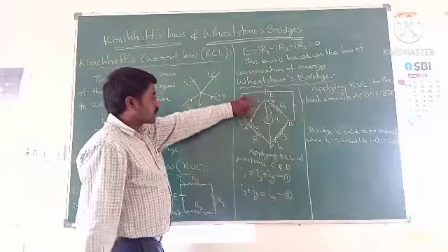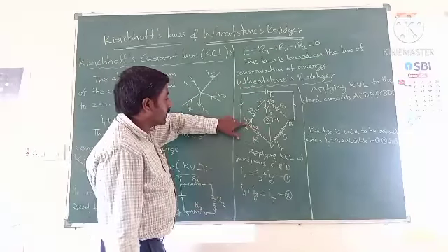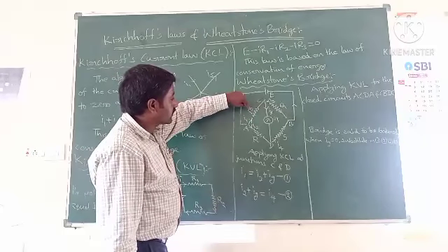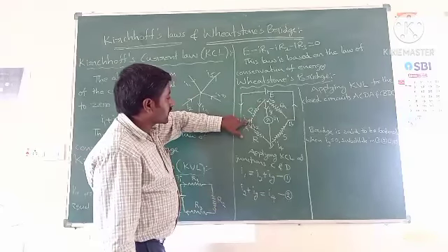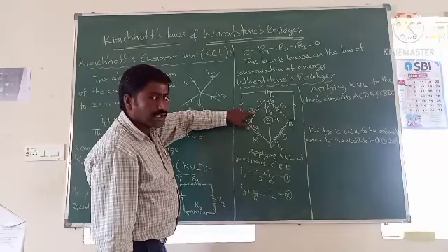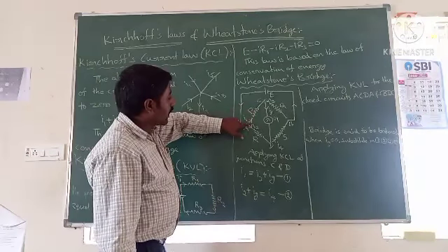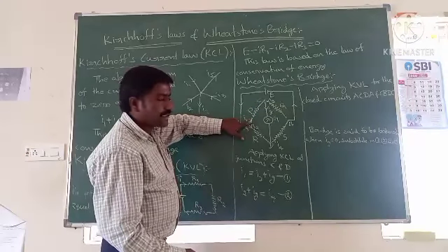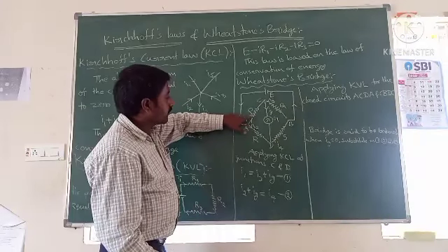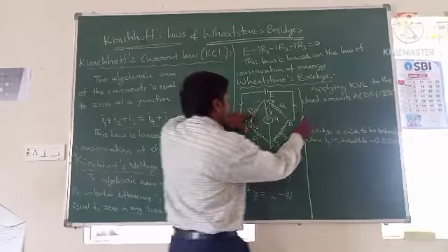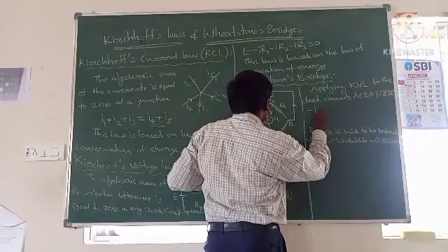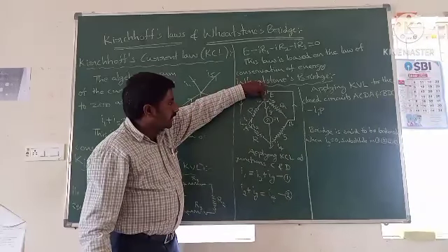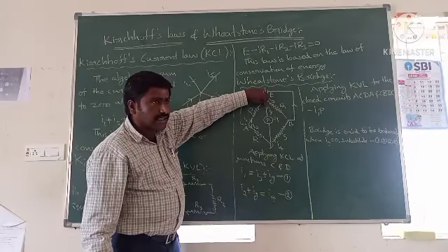Just observe the first closed circuit, A, C, D, A. I am starting from A, moving in the same direction as the current through resistance P. The current is I1 and the resistance is P. Then what is the potential drop here? I1 P. My finger direction and current direction are both the same way, which means the sign is minus. So minus I1 P.